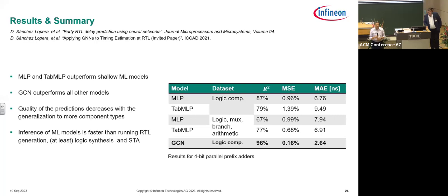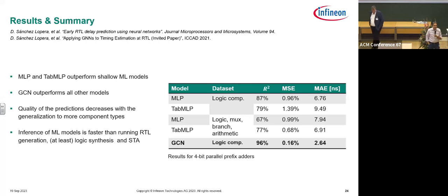Compiling for a platform means that you have a compiler in between. So you're trying to estimate the performance of your code running on your hardware, and then you have a compiler there. How do you account for the compiler, especially taking into account that in DSPs and most platforms, the compiler options in themselves are going to have an extreme effect on what is going to happen there? And just to add one more thing, in typical embedded system development environments, we're constantly changing the compiler and optimizing it, which means that whatever prediction you do is probably going to be outdated the next day because your compiler is already doing a better job today.